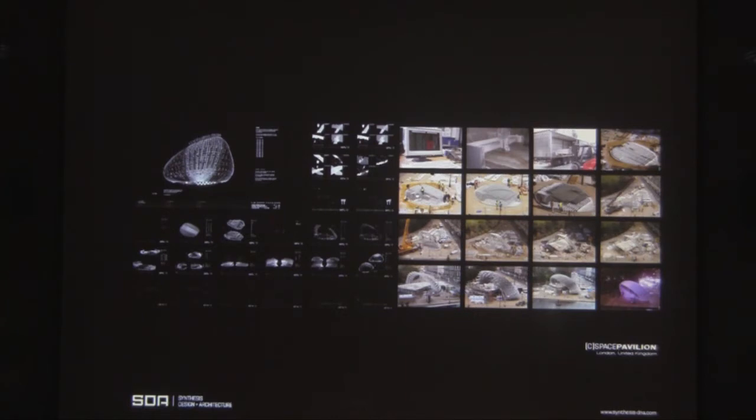The notches were identified, named, unrolled, and then sorted onto 2D sheets and nested. Sent and cut by water jets, reverse sequenced, and then flat packed into a big rig, brought out to site, assembled over a course of 8 weeks.